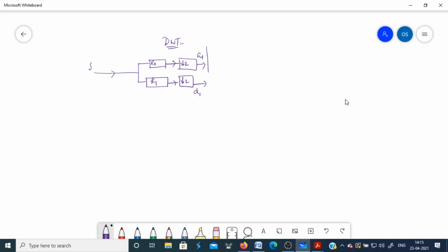Then these approximation coefficients are again processed using the same filters H0 and H1, again downsampling by a factor of 2. So you get approximation coefficients at level 2 and detailed coefficients at level 2, and so on. Okay, this is the analysis side.